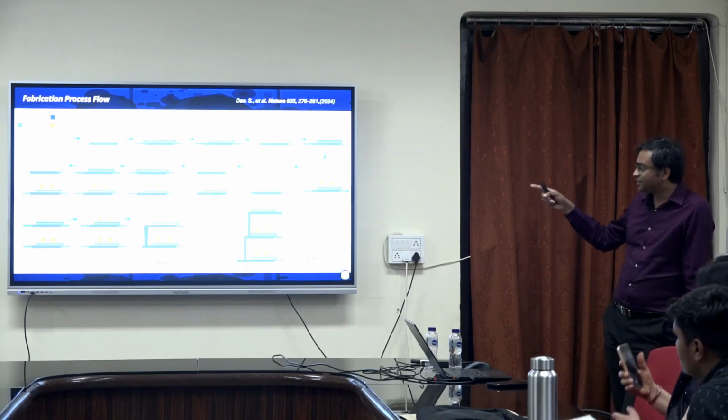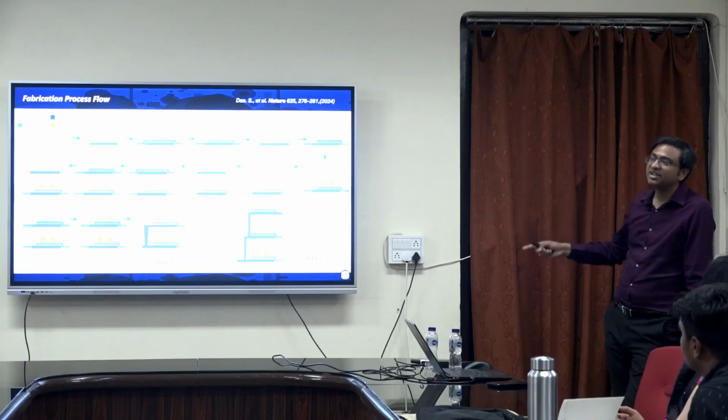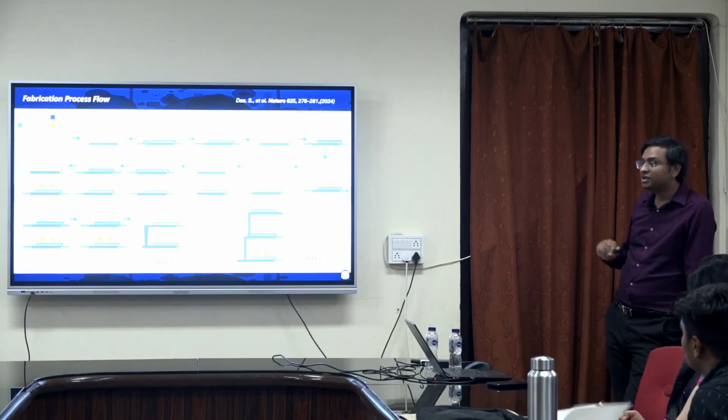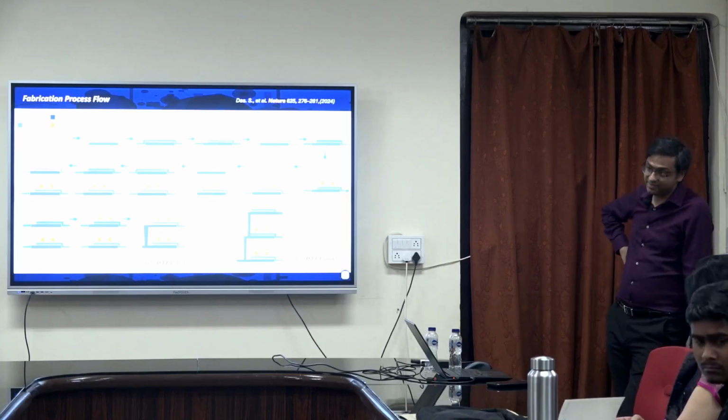And at that point, you have to start etching the inter-tier dielectric and start doing these vias. But these are no longer through silicon vias. And these vias are now very small, and they are connecting transistor to transistor, which we could not do with heterogeneous packaging industry. Make sense?